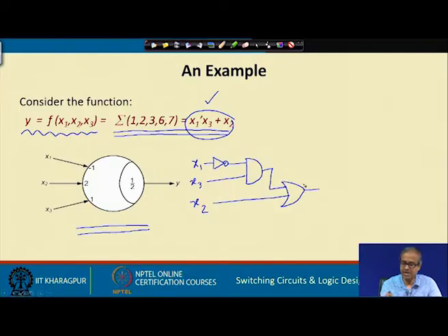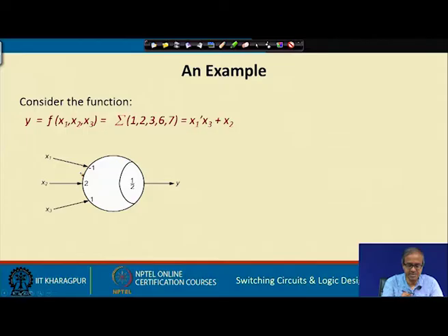So, you would be requiring 3 gates, but using threshold logic, this is just an example, using a single threshold element you can implement this function. Now, let us see how this single threshold element actually implements this function. You see here the weights that we have used are -1, 2 and +1, and the threshold is half. Let us see how this gate works.